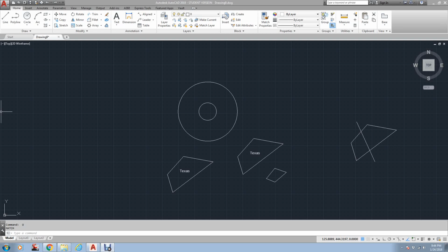I'm an instructor here in the Houston, Texas area, and in this video we'll be covering the hatching command for AutoCAD. One thing to remember, different disciplines in AutoCAD, or different industries I should say, use different hatching for different symbology. So, whatever company you go to work for, I'm sure they'll have a set of standards that they go by. The hatching command is right here, and what it requires is a closed object.